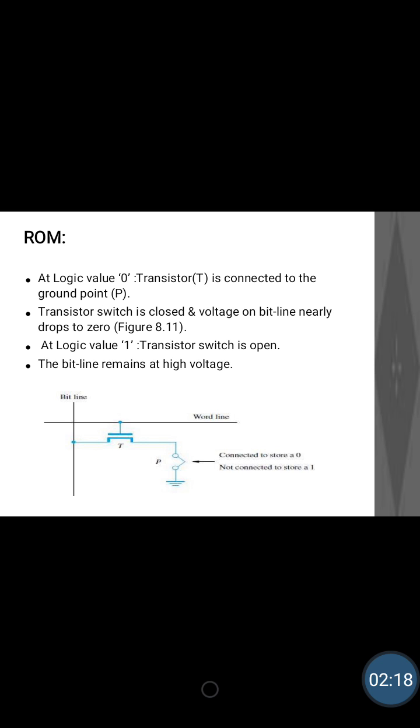That's why whatever the bit line is will be taken as 1, so logic level 1. Then to read the state of the cell, the word line has to be activated, and the sense circuit at the end of the bit line will generate the proper output value. This is how 1s and 0s are stored in ROMs.